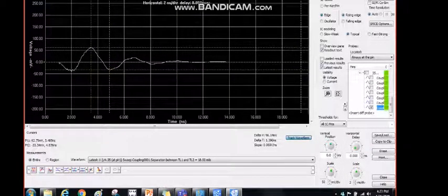The first thing to understand is that anything above 2 or 3 gigahertz of signal bandwidth, your 2D solvers will not be able to capture realistic information, or may not be able to capture the transmission line model properly. So we recommend that anything above 3 gigahertz be taken care of in a 3D environment, which can be either FDTD solutions or FEM solutions, or HyperLynx advanced solvers, which have hybrid solutions that basically work on the MoM principle. Okay, so we'll have to introduce that part.